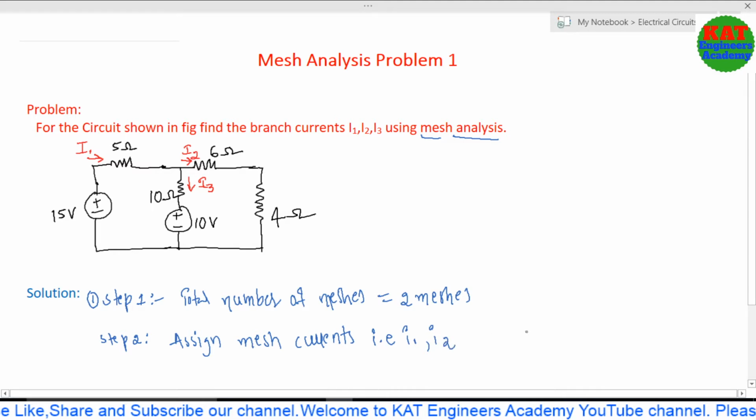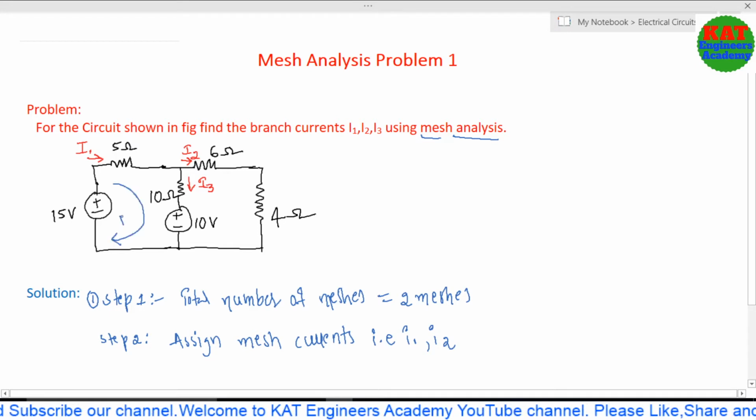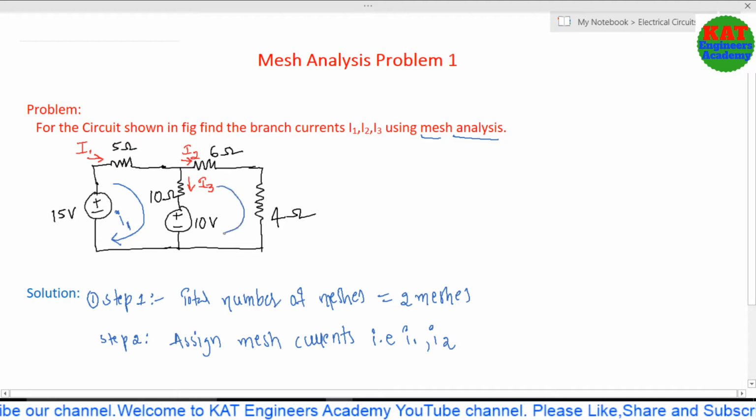First you have to assume the mesh currents. Here I consider this one mesh, this another mesh. In this mesh I consider the current direction clockwise, and this current I call small I1. For the second loop you have to consider one more current direction. You can always consider the current direction as you wish, either clockwise or anti-clockwise. So here I consider the directions I1 and I2. Now two steps are over.